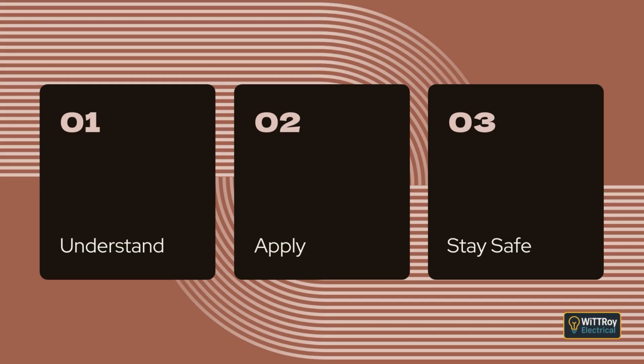There is one exception. If the only risk is damage to equipment, and the owner accepts that risk, then undervoltage protection may be left out. Clause 2.8.2, Selection of protective device. The undervoltage protective device must be suitable for the type of equipment it is protecting. It must follow the rules and the relevant standards, especially for motor starting. If automatic reclosing of the device could be dangerous, it must not reclose automatically. In other words, when the voltage comes back, the equipment should not restart if that restart could harm someone.